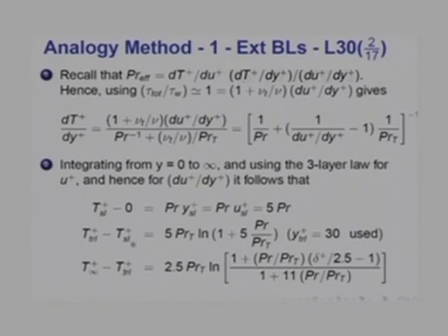And then from the edge of the transitional layer till the edge of the boundary layer, you will get T infinity plus minus T transitional layer plus. Again dU+/dy+ will be 1 over kappa y+, where kappa is 0.4, then you will get that relationship involving delta plus, the boundary layer thickness. So, we got essentially layer by layer contributions to T infinity plus.